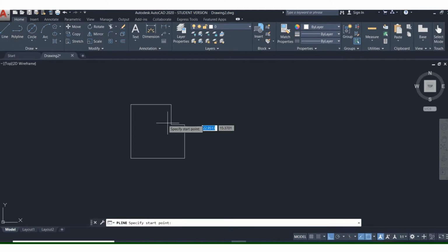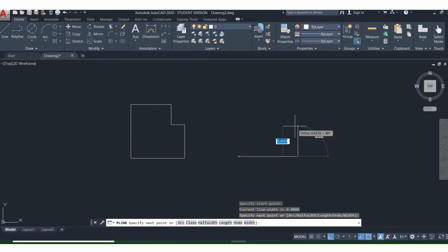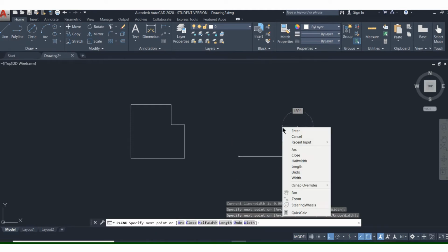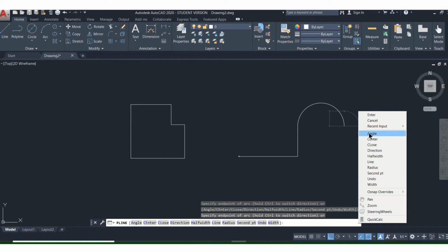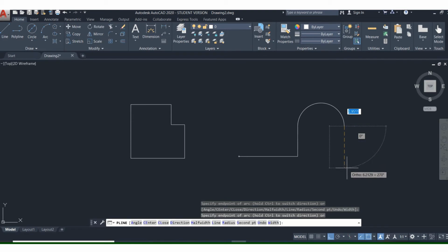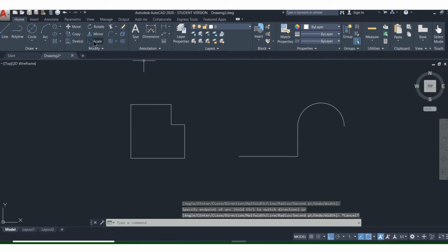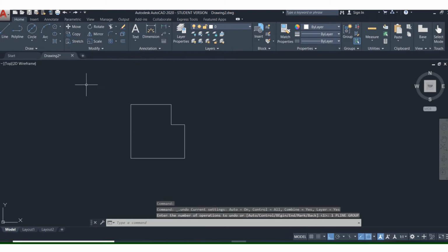Let's see, Polyline is just a line where you can actually draw arcs if you want. So in the middle of it, you can switch to an arc. What I'm doing is right-clicking and then using those tools in there, if you want to make a straight line or you want to make arcs. So Polyline is just like a continuous line. I usually don't draw with polylines.